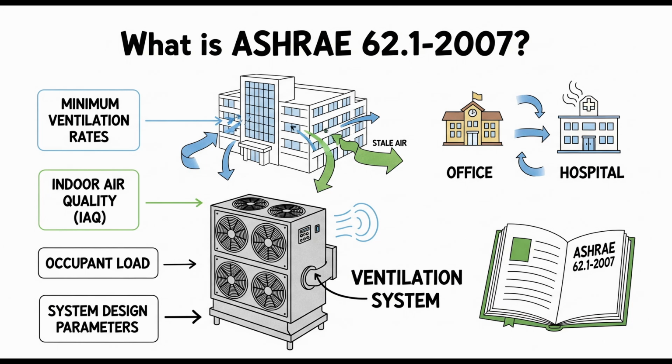Right. But if you supply warm air from the ceiling and also return it near the ceiling, that warm air might just pool up high and not mix down well.